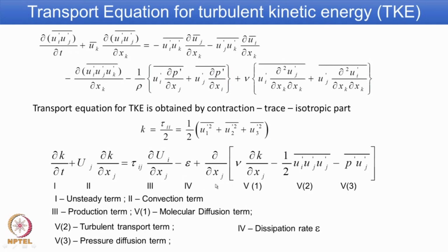the dissipation term. So, in today's class we have learned the first stage in turbulence modeling, starting from the transport equation for each Reynolds stress term and how to get the trace of it to obtain what is known as the transport equation for turbulent kinetic energy. In the next class we will start from here and do actual modeling for those additional terms in the transport equation for turbulent kinetic energy, and we go into the standard k-epsilon and k-omega model expressions and explanation.